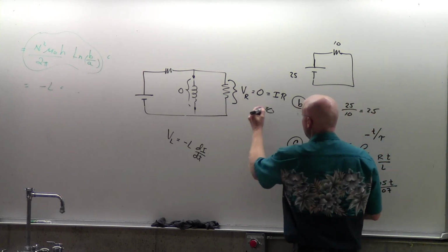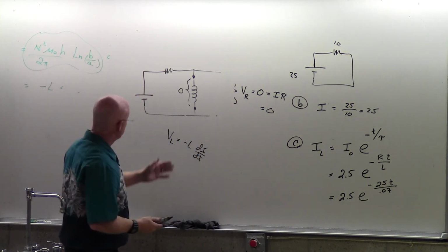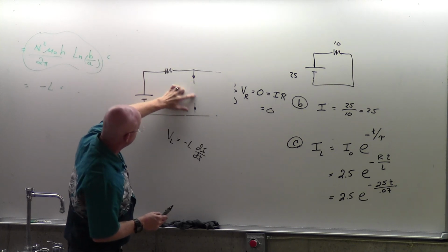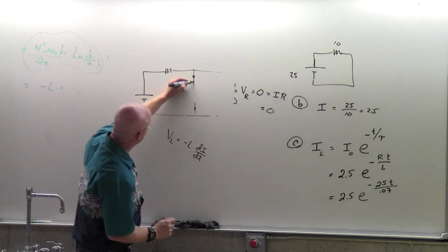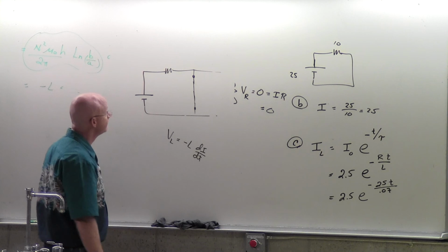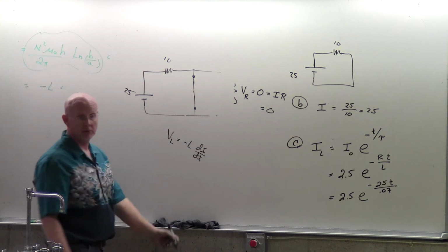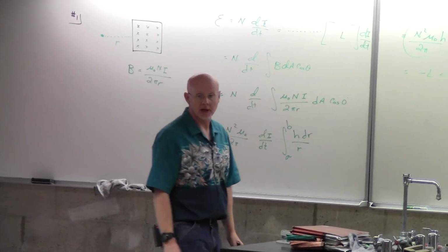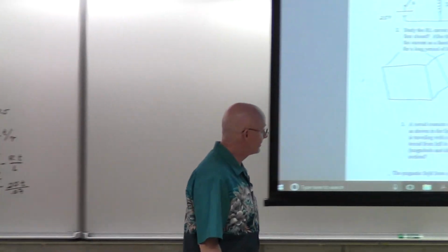0. And so it is basically saying this isn't here because it's free to go through this path. And in fact, the flux from the inductor has stopped doing its thing, and so now it's just a wire. And so that's how that circuit came to be. And so then it's just V divided by R after a long period of time. All right.